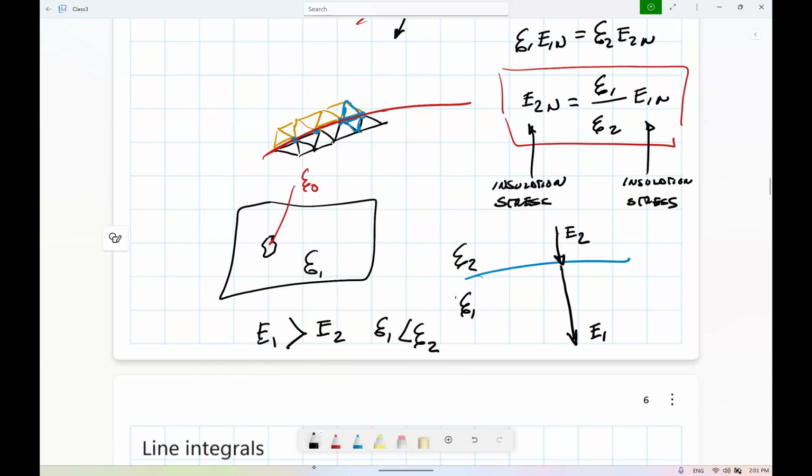You can create a stress zone by the change of insulation. But sometimes you need to change the insulation. You can't keep everything together. For example, I have to go to the transformer because it's what I know best. In a transformer, you have oil-impregnated paper insulation touching the conductors. But paper is not a very good conductor of heat, and the transformer is going to get hot. So you need to remove that heat. So what you need is oil.